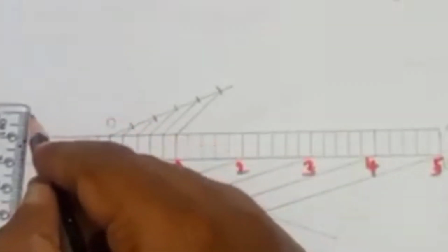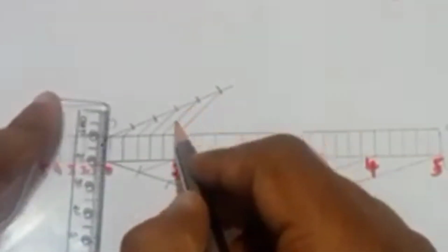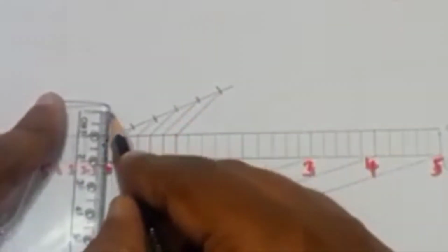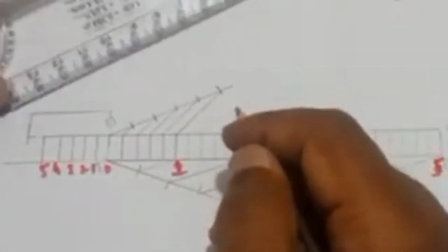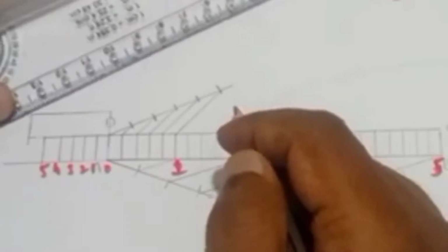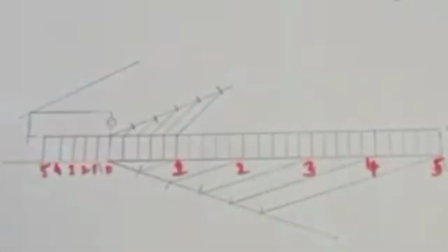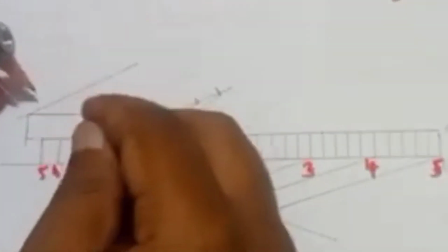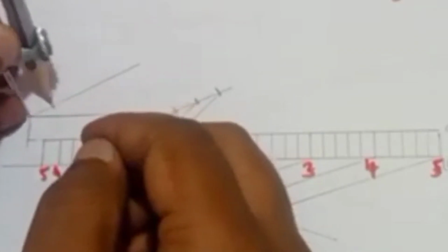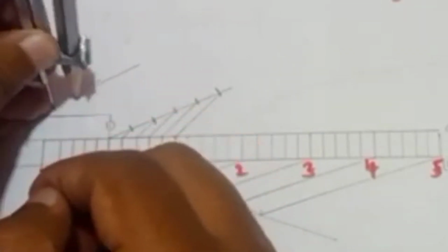So here what we have to do is, after constructing a box of 6, we have to divide it into 5 equal parts. So when we do that, each part will get a length of 1.2 meter. Okay, that's what I have written there. 1.2 meter into 10 is equal to 12 decimeter here, each box. Again, for dividing into 5 equal parts, again I'm drawing an angle line. Again taking compass. Here the same thing we are doing, dividing this 6-meter box into 5 equal parts.